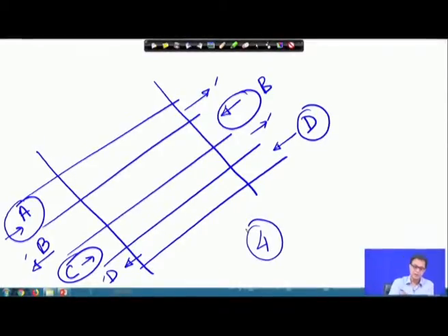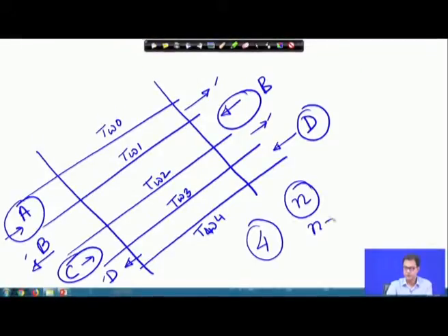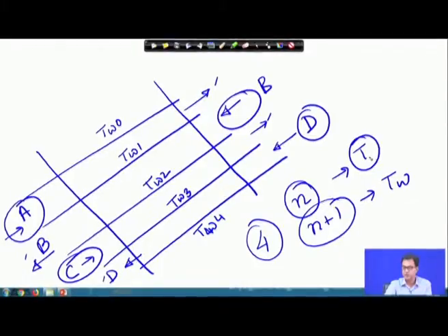Then, what else is not known are the wall temperatures, say TW0, if we designate it, then TW1, TW2, TW3, all these wall temperatures also matter. So, we have n number of fluid streams whose exit temperatures are not known, and we do not have information about the wall temperatures for the n plus 1 number of separating plates.